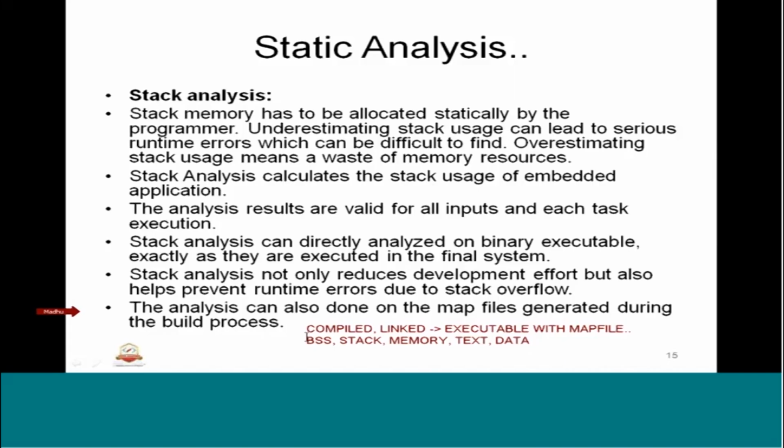So that needs to be analyzed, and we know with the help of the map file what the stack is. So maybe as a practical example, I will try to go through a sample memory file. The memory file will have a name with a dot map. So this needs to be analyzed statically. So with the help of that, we will know the memory aspects and the stack aspects of the embedded software program.